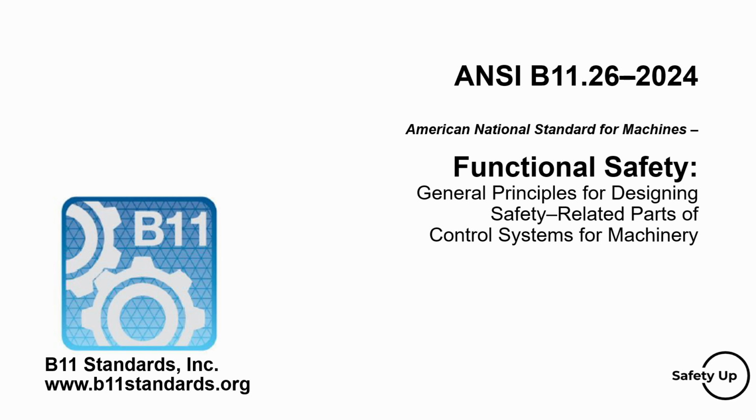The General Design Requirements section provides overall design requirements for safety-related parts of control systems, regardless of the required reliability. It covers integrating SRPCS in the overall machine controls, specific functions like protective stop and start functions, and design requirements for electrical, fluid power, and mechanical components.